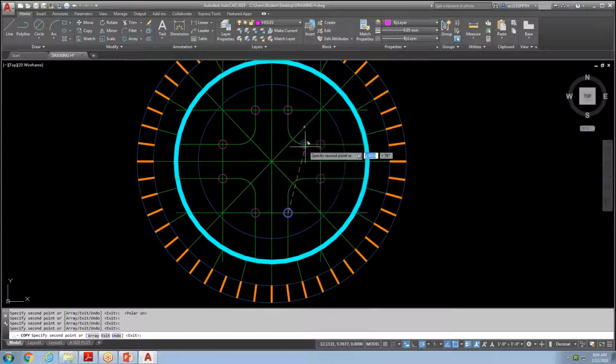And then I got a couple where I actually want to have these center right here. So what I'm doing is I'm touching this here and picking up that tracking point. And when it does, I can put it there. I can do the same here and pick up this tracking point. And that's using object snap tracking. I'm just touching it here and pulling it over. And it actually finds that point. So I touch it here, and then when it intersects there, we're good to go. And all my little circles are there. Now that's object snap tracking, and you're going to need to practice it because you don't actually click until you have it over the location, but it gives you automatic tracking.